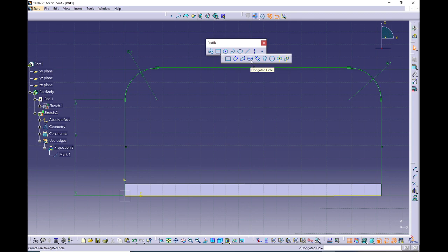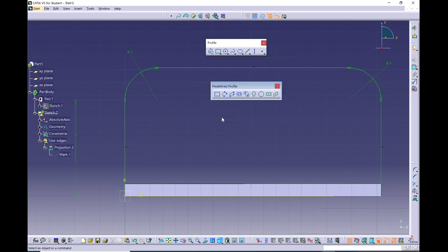One thing you can do when you go to the pull down to get a sub toolbar, you can actually grab it by the handle and drag it out and make it a permanent toolbar. The reason we have all these sub toolbars hidden is because if you were to have all these toolbars along the periphery of your window in CATIA, that would just be commands all over the place and buried, and you would have to go look for them. So you could just simply go to the pull down.